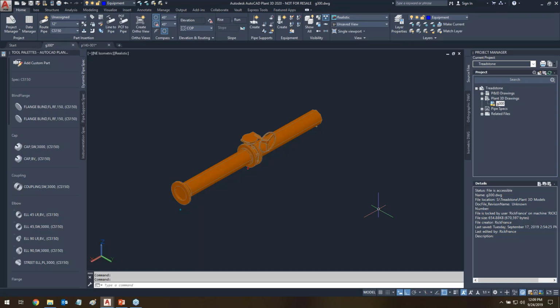fix. Now, initially we have to have what's called an encode that's available to be able to connect this up. And since I can't use the WF encode because that one out of the box already has gaskets, and if I remove the gasket and set this up on that one, any of the butterfly valves, for instance, that I put in that are wafer valves that are out of the box aren't going to work correctly because they possibly may need gaskets, because you can buy wafer valves both ways. So this is a unique situation where I need a whole new set of encodes and connections to make it